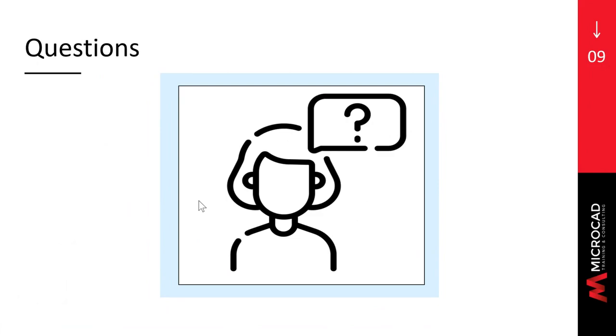So right here, what I would recommend is that notice that this one has been scaled, right? So you can go to your tools, you can go to measurements. And if you don't see the icon for measurements on the measurements panel, remember you can always hit help, find tools and commands, and right here, oh, measure.